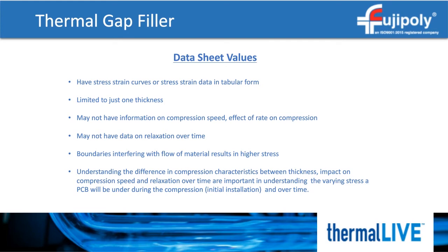Other factors to be considered when looking at a data sheet is the rate of compression. Gap fillers are highly dampened, so the rate of compression will play a big part on the peak stress. Stress is at its highest when the pad is undergoing compression and begins to relax immediately after. Communicating this to the manufacturing team is very important. Boundaries also play a big part.